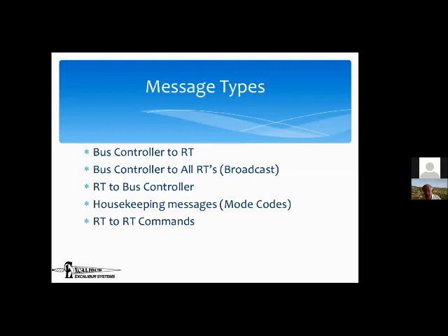The 1553 spec doesn't talk at all about what it is you're supposed to communicate. You can think of the spec as being a specification for a telephone in which you don't tell people what to say. Other specs are not like that. 429 actually in the specification tells you exactly what to say. Well, some do and some don't actually.